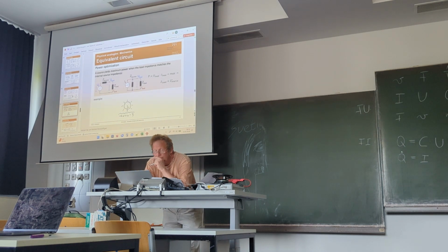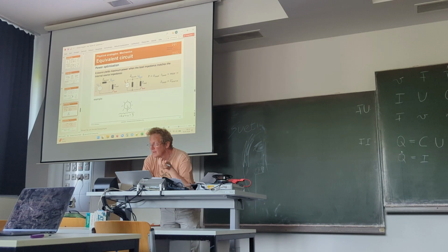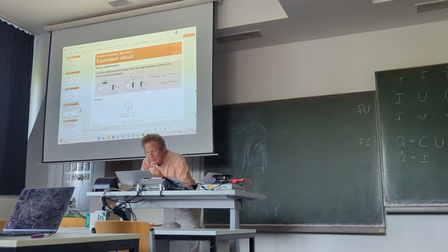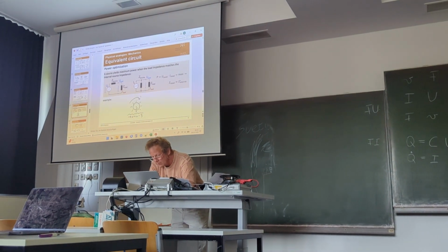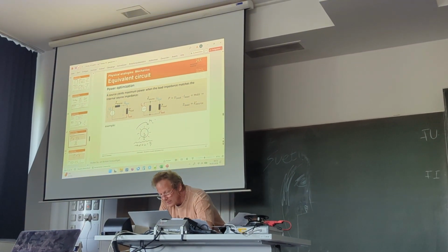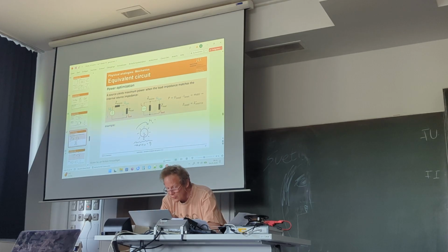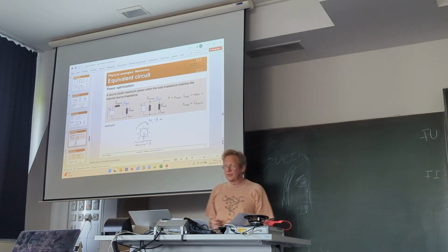Then on our water wheel we have other moments. We have a load, for example, the power generator acts like a load, and that means we have a moment. And this is typically proportional to omega, so this is a beta times omega. Beta is a damping constant.